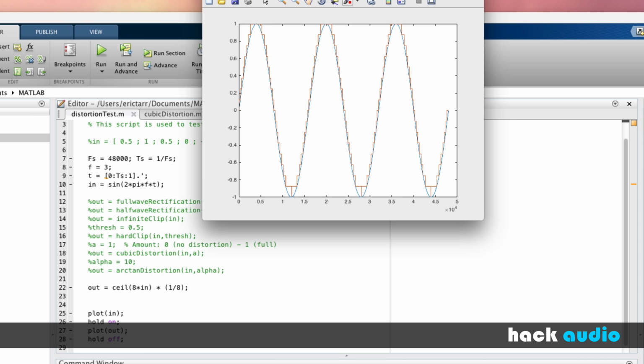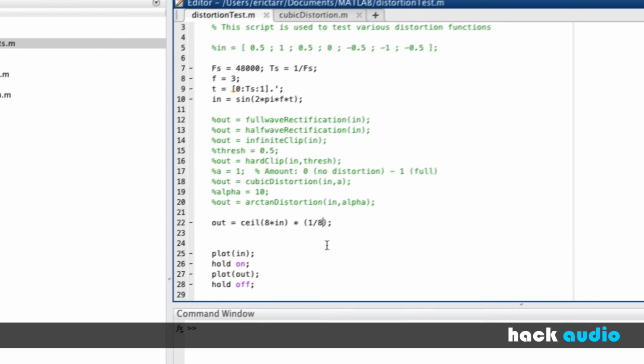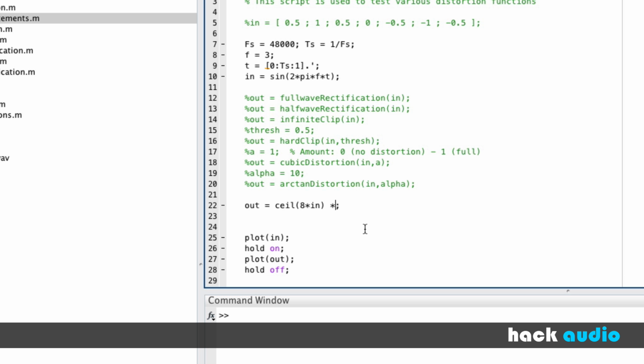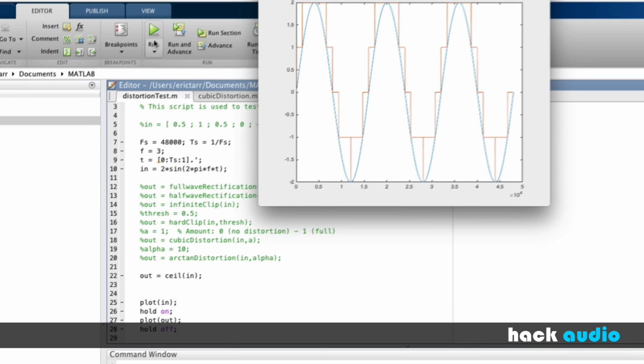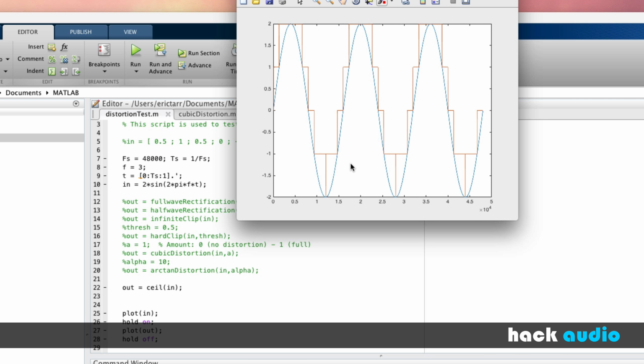So the relationship here, if I want to demonstrate this, let's go back to what we had initially. If I multiply here by 2, what does this look like? We stretch things out. We get 4 amplitude levels, which is the same thing as 2 bits. So for our number of bits, think about amplitude in terms of 2 raised to the power of the number of bits.